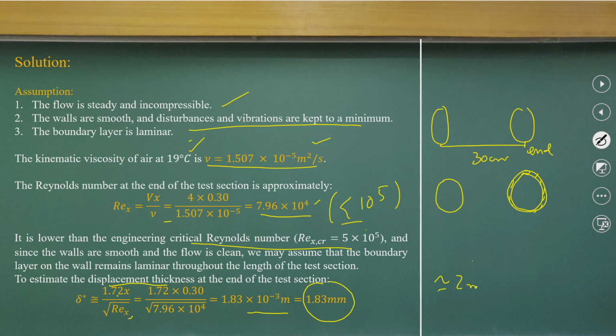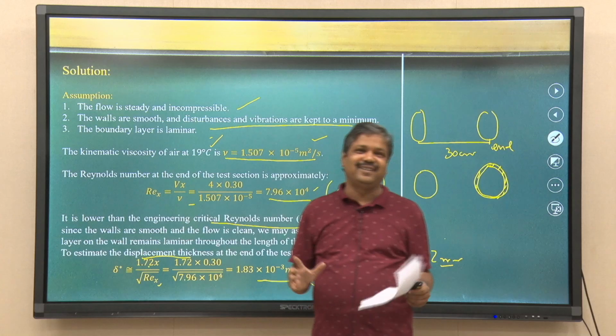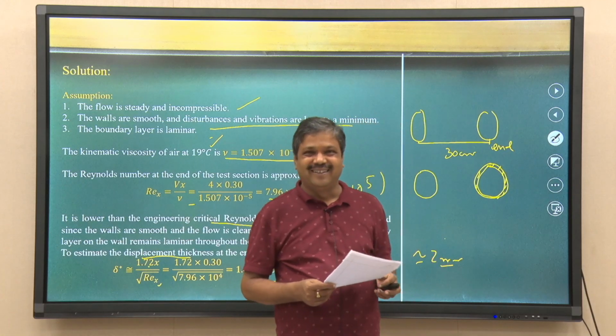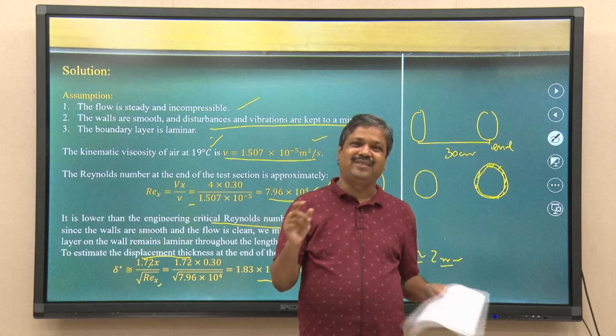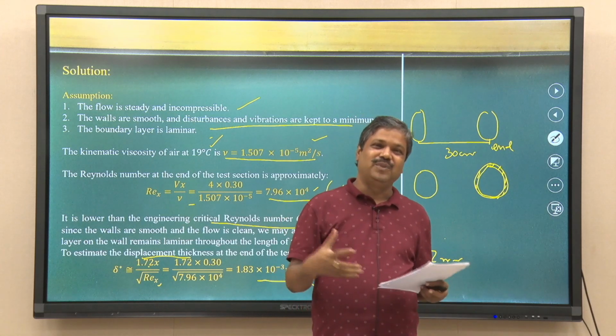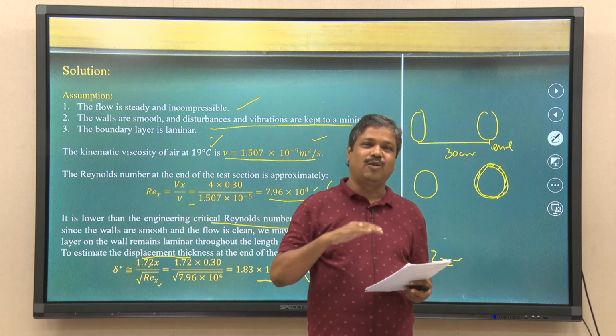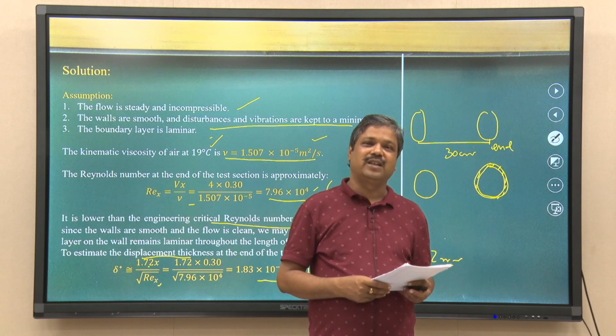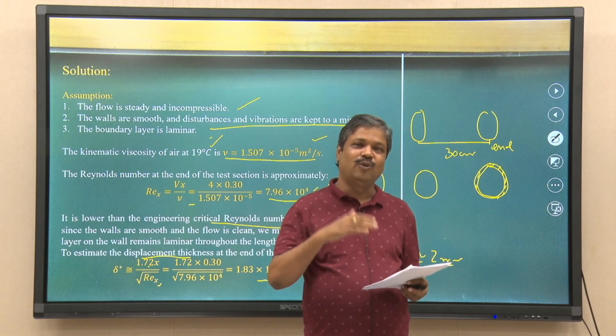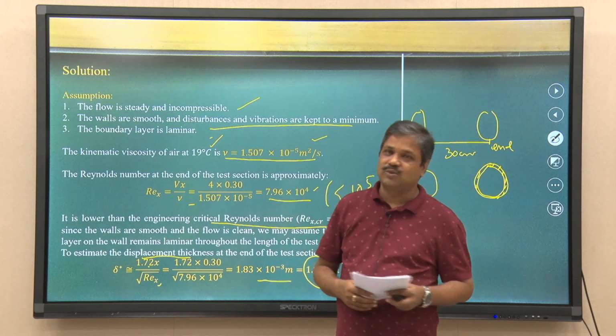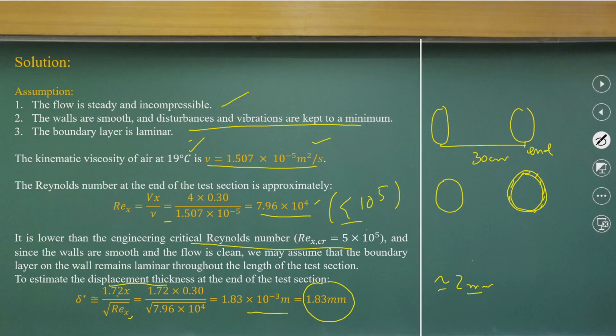Just look at it, as I demonstrated, it is not visible. Mostly we ignore that part, but that is what majorly controls the boundary layers, how the drag force or lift force are happening, and how the shear stress distributions are happening. But the thickness, as you saw in these examples, is in the order of millimeters, while the diameter is in terms of centimeters.